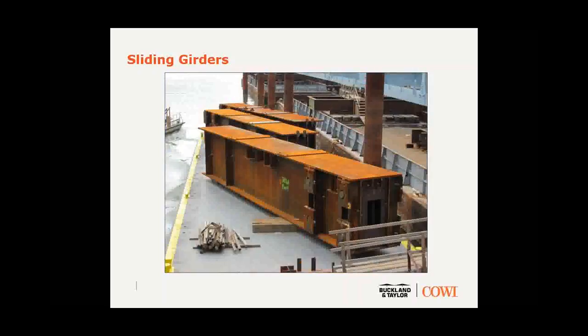These are those sliding girders, all three of them sitting on a barge, 101 inches deep, 78 inches wide box girder with plates up to 2 3/4 inches thick. Each of these weighs close to 100 tons in its own right, and took a lot of care to fabricate and erect. They have heavily stiffened top flanges because the entire length of this girder will receive a truss bearing sliding along it with around a 4 to 5 foot square sliding footprint.